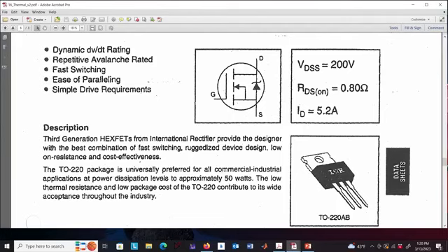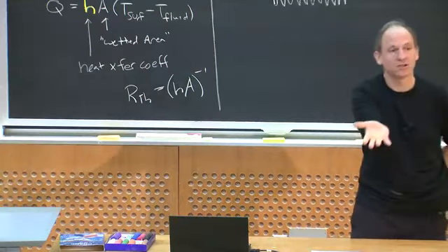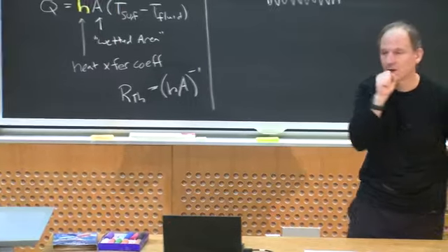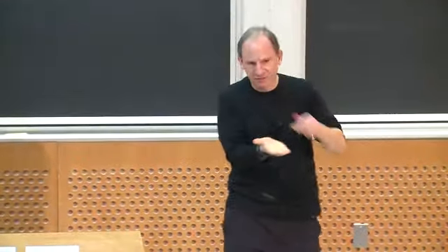These leads, gate, drain, and source, are connected to the device. And then one side of the device is connected down onto this pad through which you're going to transfer heat. So that's the case of the device. Inside this package somewhere, I'm dissipating heat, and it goes to the case of the device. Then I'm going to mount the case of the device down to some heat sink, but there is some interface to the heat sink.